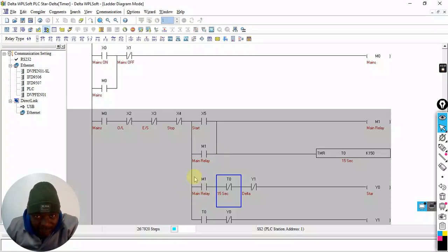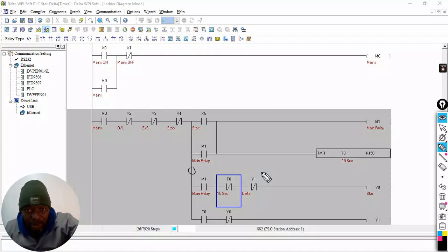So what I could have done is take this line here. Let me rather use a pen so that people see what I'm talking about. I could have taken this line there. Then I wouldn't have had to put that one there, because it's already controlled on the other side of the start. I could have drawn all these from that point. It doesn't really affect the timer, because it can never go on until the timer says so. So I don't have to move it, but that one definitely had to move to after the start, not before. I hope you understand that little thing we overlooked.